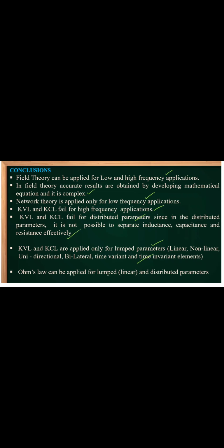But Ohm's law can be applied only for linear. Lumped and distributed, we can apply. Ohm's law is applicable for both lumped and distributed, but only in the linear case. It is not applicable for the non-linear case. KVL and KCL are applied for any case, but the condition is lumped. Ohm's law is applicable only for linear, but it may be lumped or distributed. KVL and KCL are only for the lumped case, not for the distributed case.